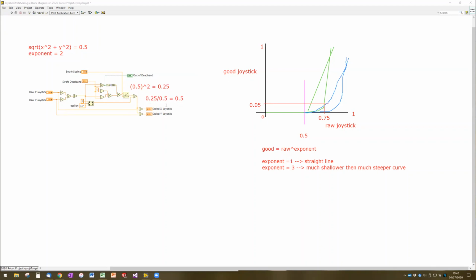And then we would multiply the X and the Y joystick values both by 50%. And so we would scale them both the same. And so then when we go to do the arc tangent, at some point we've got to do this arc tangent to get the goal angle. So we've got angle equals arctan of y prime over x prime.